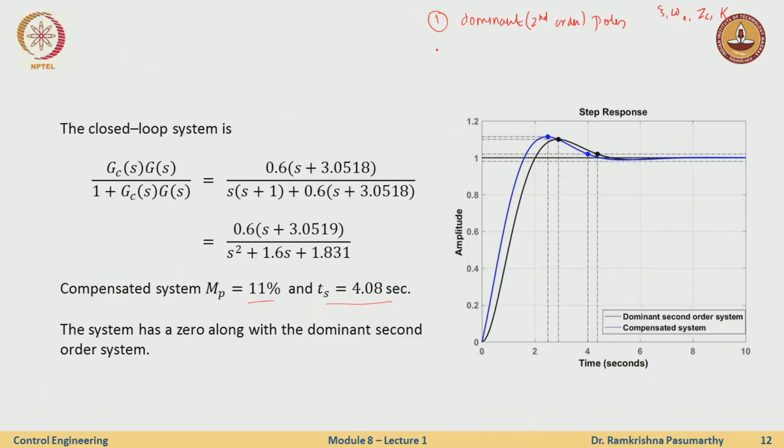Now in addition, I add the compensator, so in reality this is not true. My dominant pole analysis is based on this kind of transfer function, omega n square over s square plus 2 zeta omega n s plus omega n square. In addition, I have a 0 here, so the plot will include the dominant second order poles for sure, plus the effect of the 0.